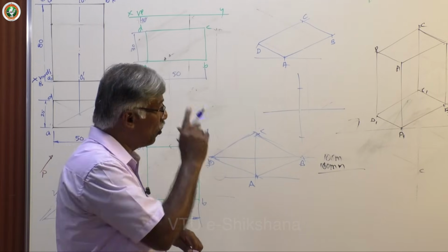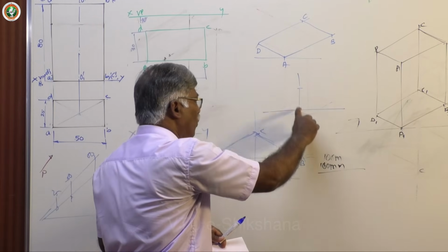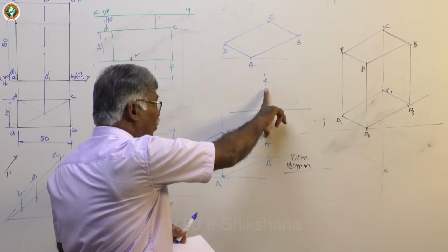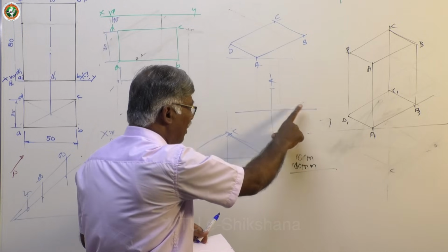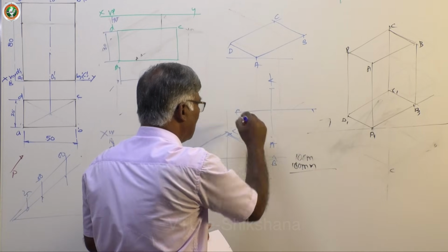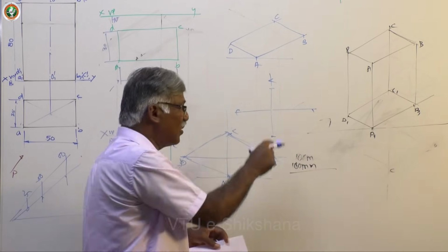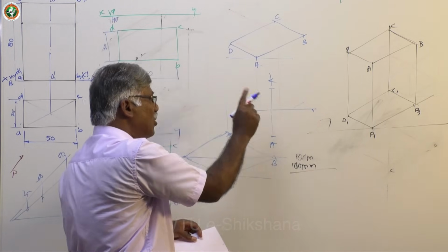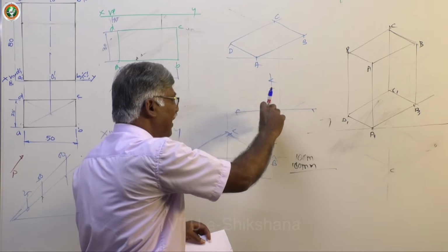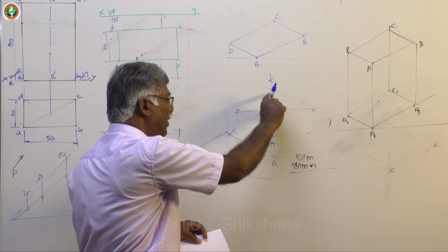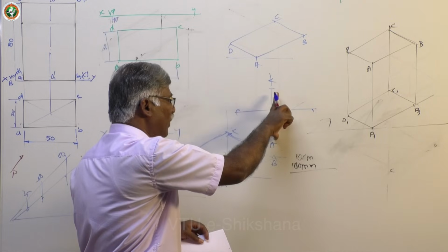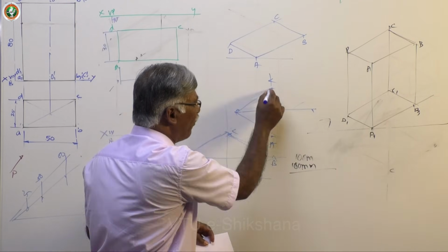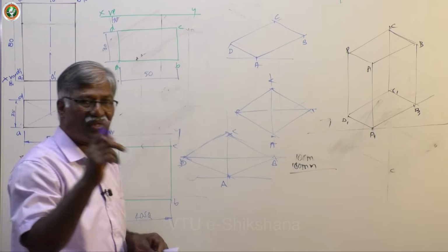Then take the total. This is how you draw this. You got AC ready. Then take the total. Don't lift the compass. Draw towards either side. That's all. If you lift the compass, there is a tendency to move to this point and draw arcs. This is the most dangerous point here. So don't lift the compass. Take half, that is 20-20. Take the total length from either A or C. Draw towards either side. Definitely you get a rhombus, that is exactly the isometric position of a square.